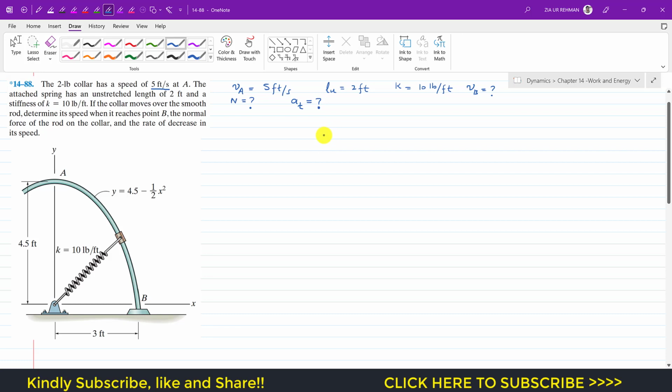Now to find the velocity at B, we have to apply the law of conservation of energy between point A and B, which says that the kinetic energy at point A plus the potential energies at point A will be equal to the kinetic energy at point B plus the potential energies at point B. So at A, the velocity is 5 feet per second, so the kinetic energy at A is 1 divided by 2 times mass. Mass is the weight divided by g, which is 32.2, times VA square. VA is 5, so that is 5 square.